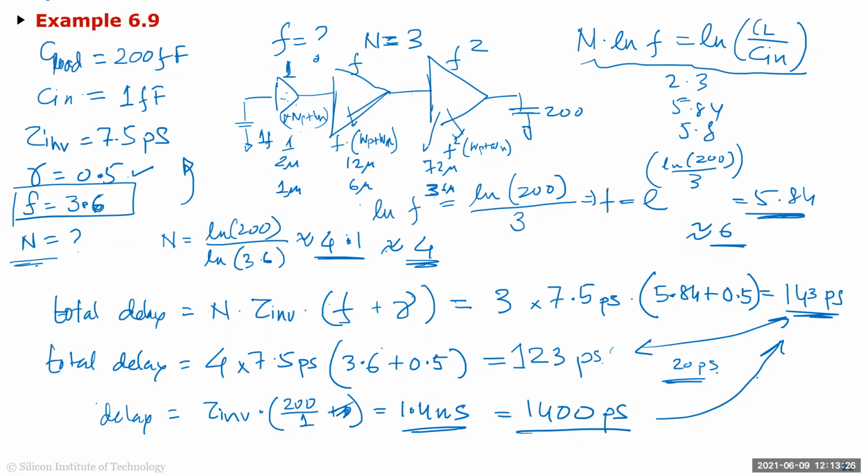Okay, is everyone clear on what we did here? Essentially we just took an example to see this. This is something you do a lot in design. When I'm designing, usually I don't bother calculating. I just do 3x or 4x fan out, put 3 stages and I'm done, because I know it'll be a few picoseconds off here and there.